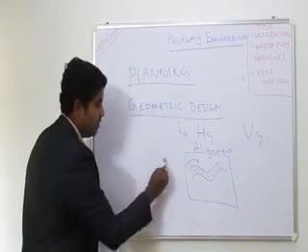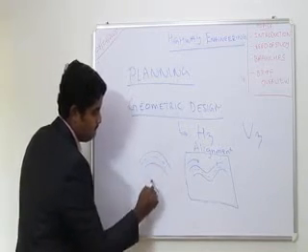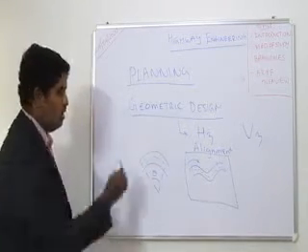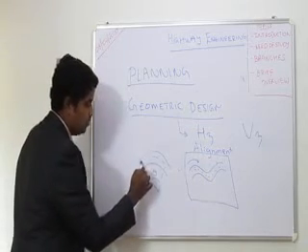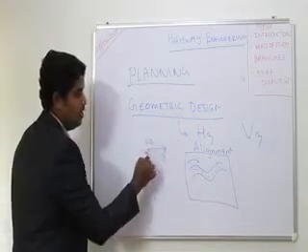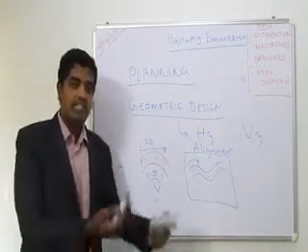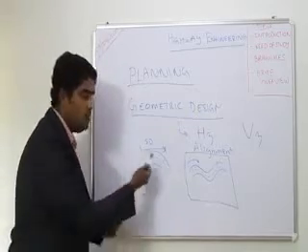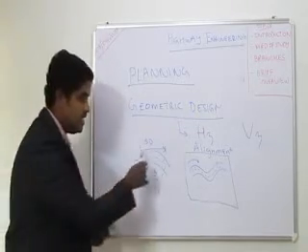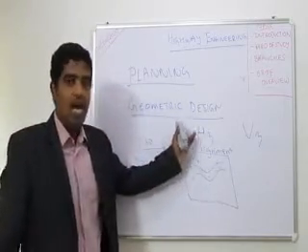How large can you make the radius of the roads, or how far can we see from here to here, what is the sight distance? How can we see an oncoming object or oncoming vehicle, or an object stationed at a distance, and how fast can the vehicle go so that he can see the object in front of him? All those things will be studied under horizontal alignment.